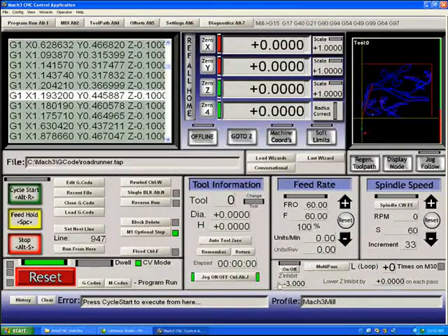This section of the screen here is used for multipass. Again, you don't need to worry about it unless you know how to use it. Generally though, if you have a GCode file which is set to a particular depth, say it's set to cut to -10, you could hit multipass and tell that file to cut 5 times, dropping 2 each time until it hits 10. So it is literally a multipass selector, allowing you to cut a file in multiple passes.